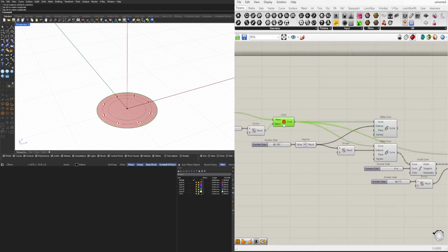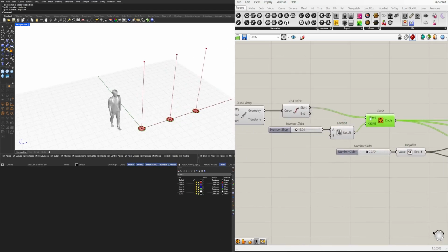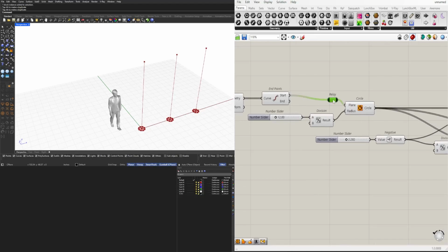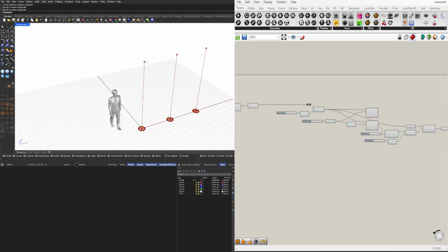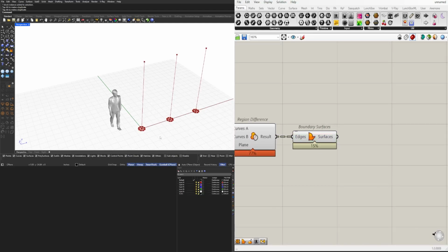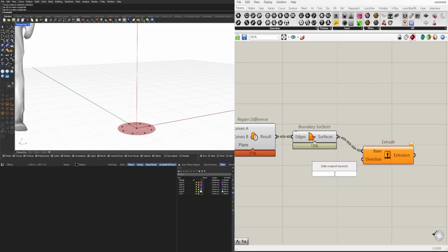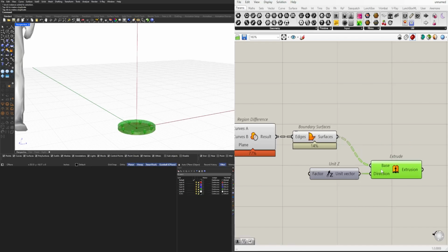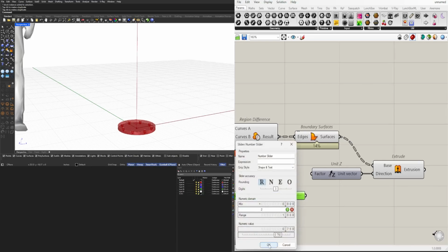Now what I want to make sure to do is that whatever circle I inputted, like so I input this point as the circle, well, I want to keep this separate because I need to do this again to the top one, but in the negative direction. So with that being said, let's extrude this up in the Z direction. And then we'll go here to .75, but then we'll change the max here to 2.